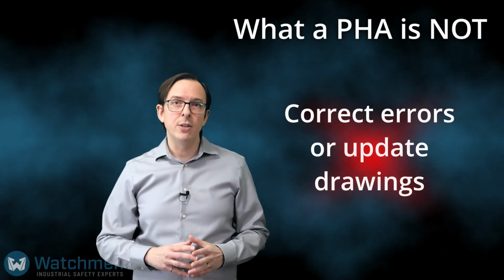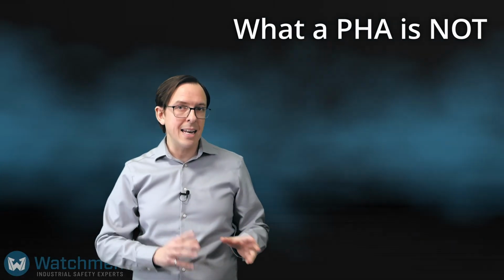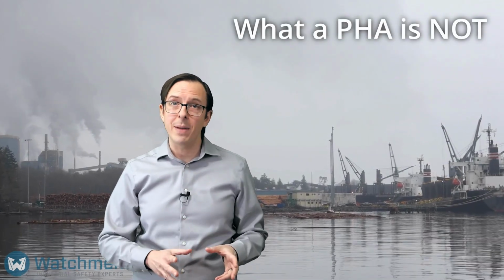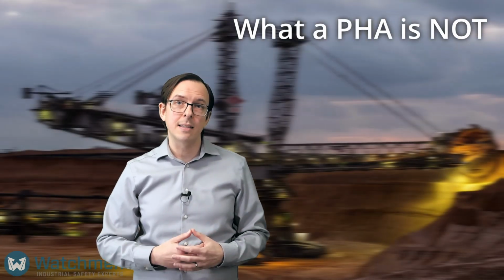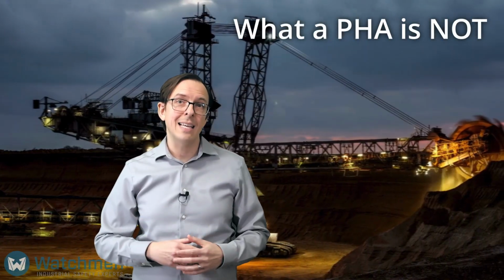PHAs are not an opportunity to correct out-of-date or incorrect documentation. The documentation must be accurate and up-to-date. If there are errors in that documentation, the team may be making decisions based on flawed information, which can lead to flawed conclusions and potentially undiscovered risk. In some extreme cases, we may be required to halt the session until a time that the drawings can be updated.